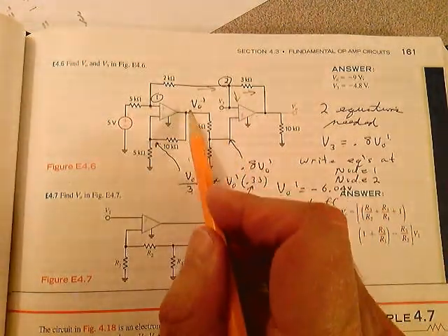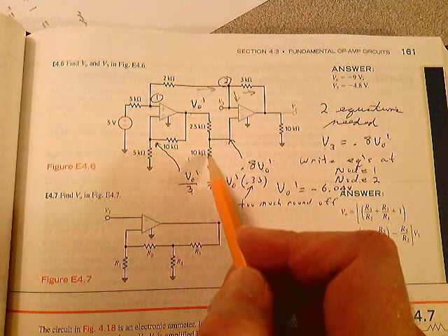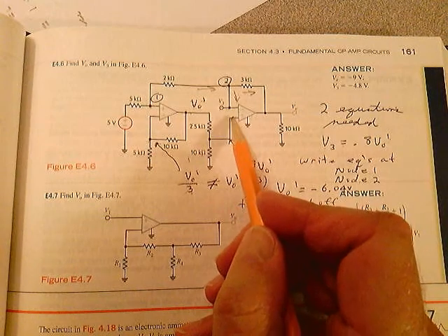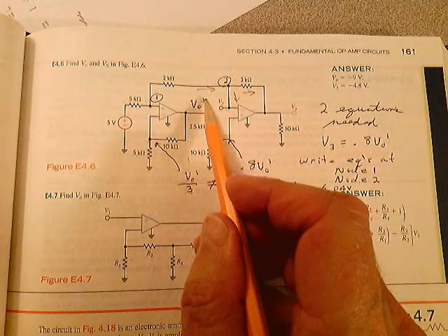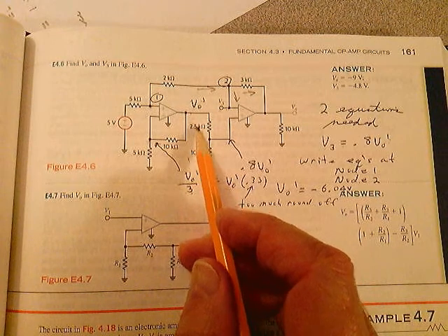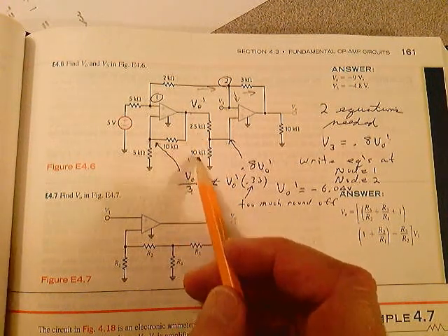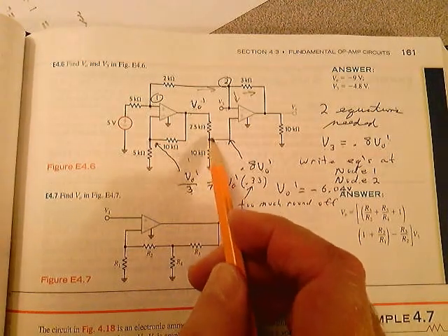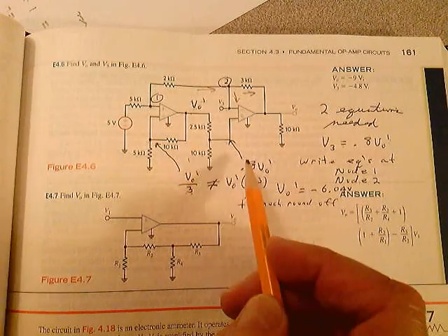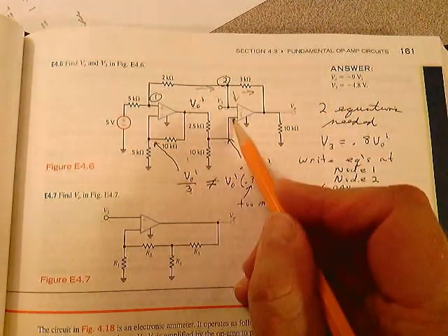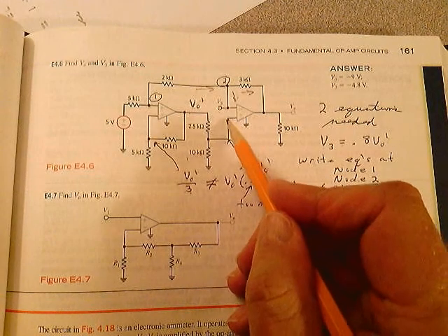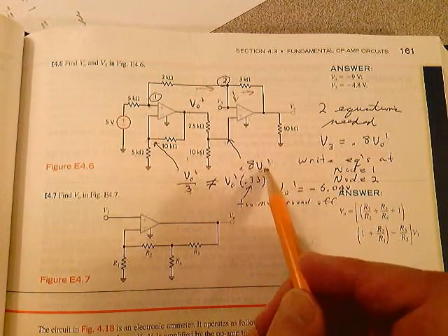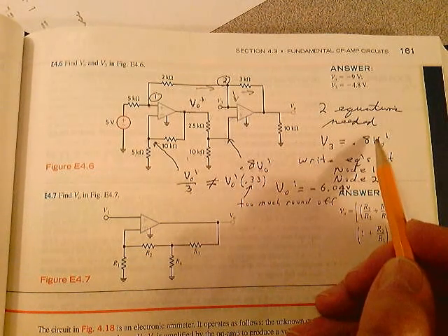Now, if that's V out prime, that's a voltage divider there too. So I'm going to find the voltage at V plus right here at this second stage. It's just V out prime times 10K divided by 12.5K. Look at that. V out prime times 10K divided by the sum of these two is that voltage there. That's 0.8 V out prime. This voltage here is 0.8 V out prime. I'm projecting it up to here. So I know that V3 is simply equal to 0.8 V out prime, right there. I know that. I'm going to use that later.